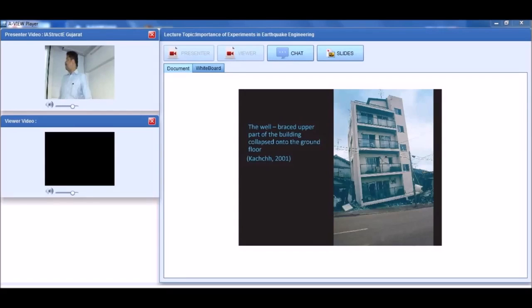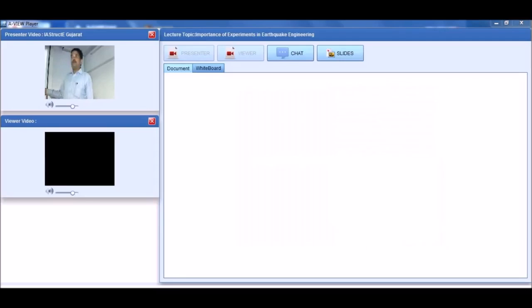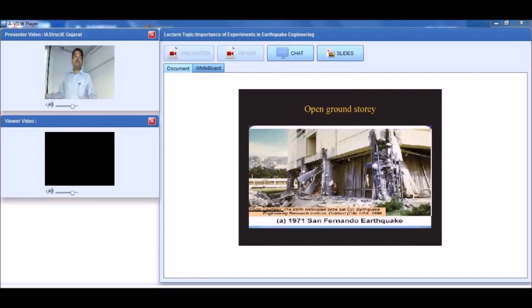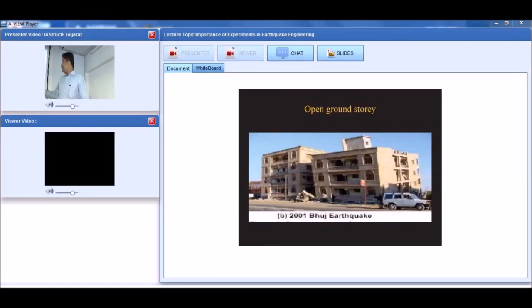Next, you can see again here glass panels are provided and it is not going to provide any stiffness to your building. Upper portion is having the brick walls. It is stiff. Ground story become flexible. And you see, this is the power of nature. Within 2 minutes, it identifies what the soft story is. Right? Within 2 minutes. Next. You can see this height of both the buildings were same. Almost it came down on its knee. Right. Ground story columns were collapsed.